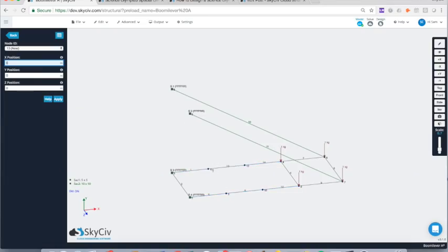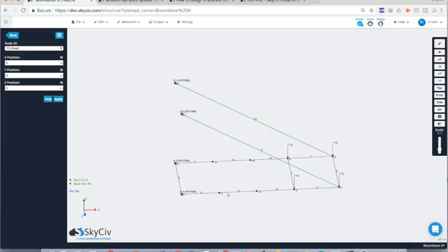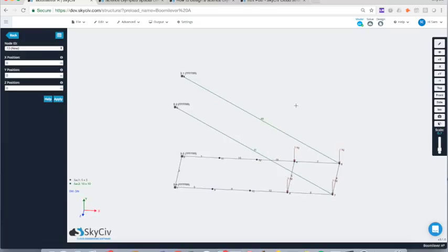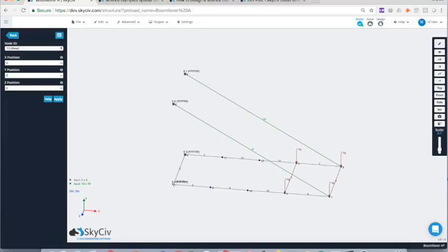So we can see it's divided, added some nodes and divided each of those members into 3. And then let's increase the strength just by clicking and dragging between the nodes. Let's create some cross members just to create some bracing in this truss structure, and that'll add more rigidity to it. So just keep clicking through. And the last one.